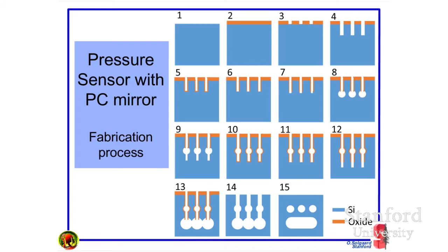That's just an idea we got from the DRIE, right? I remove things from horizontal surfaces. The top surface doesn't matter because it's already covered by such a thick passivating layer. And then I etch a little bit further down into the silicon with a directional etch. And in number 8, I can complete the thing with an isotropic etch that creates these little spheres for me, these spherical hollows.